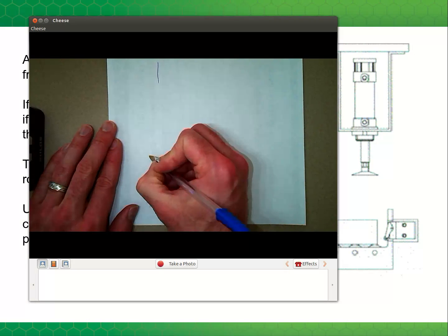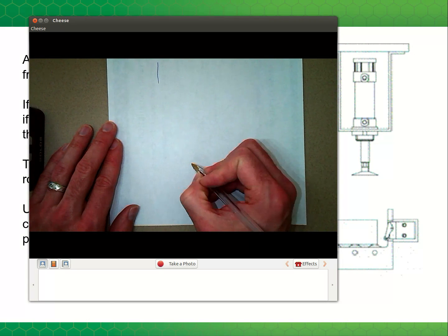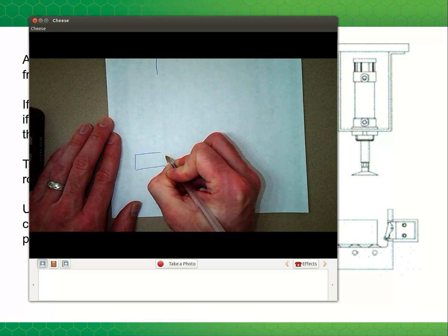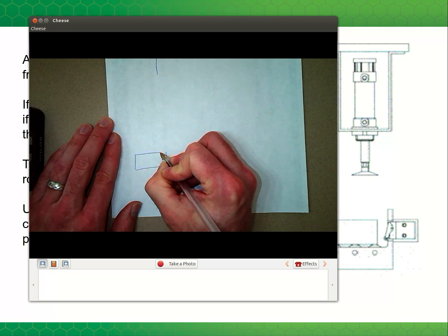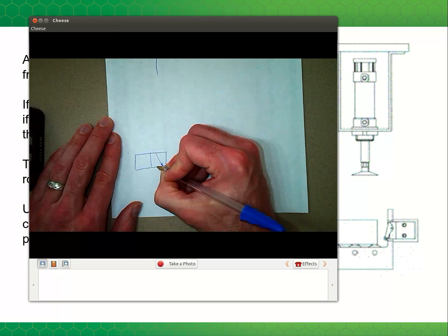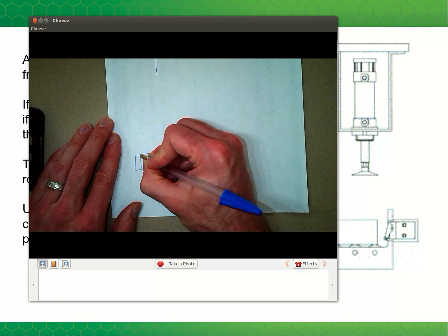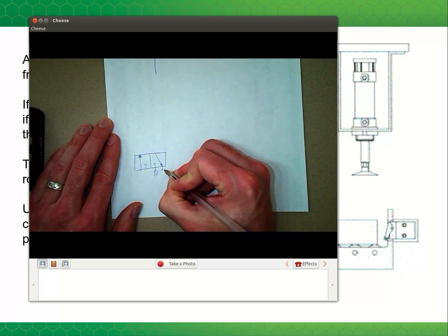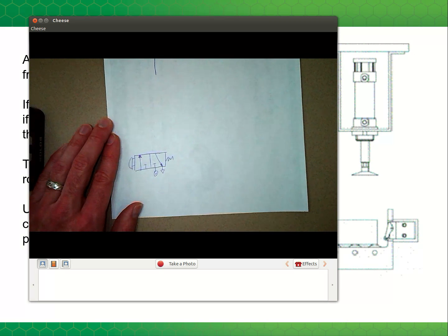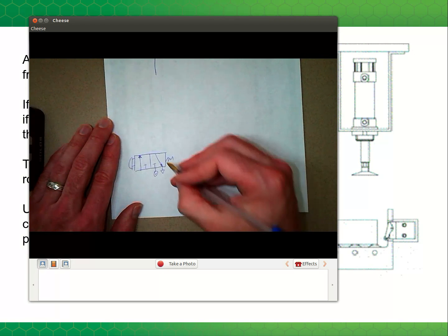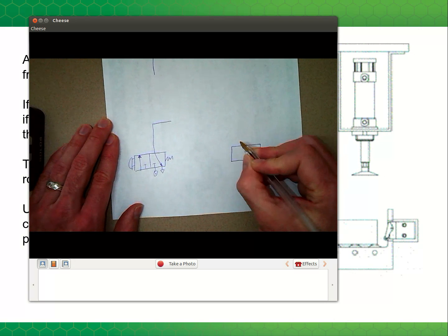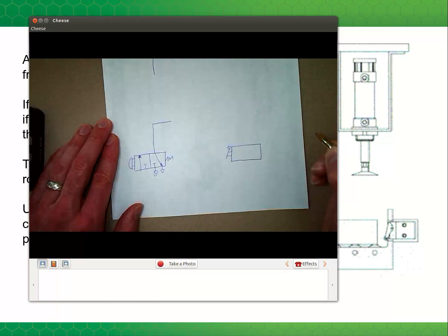So first of all, I'll draw the push button. So this will be a 3-2 valve with a push button. So there's the operator's push button. And then the other valve is another 3-2 valve, but it has a different actuation type. We've got that lever, limit switch.